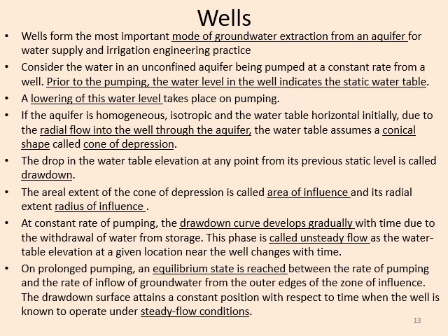So first an unsteady flow condition will occur, and with time when an equilibrium state is reached, a steady flow condition will be attained in the well, where the drawdown or the decrease in the water table will not happen further.